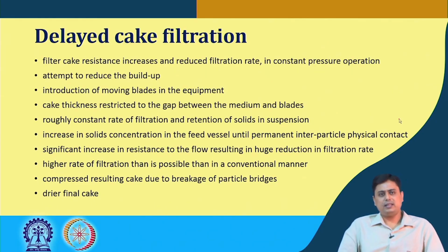So, in such cases, roughly constant rate of filtration can be achieved, and then this cake that is now removed after scraping is retained in the suspension. So, what happens with time, since these solids which were depositing as cake are now retained in the suspension, the concentration in the suspension increases with time, or in the feed vessel,